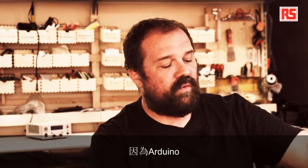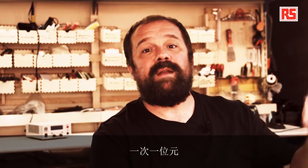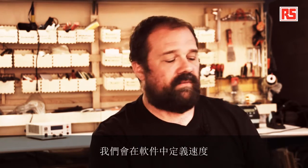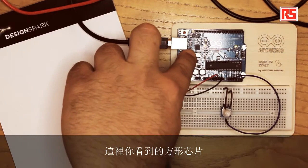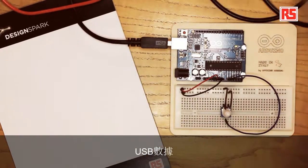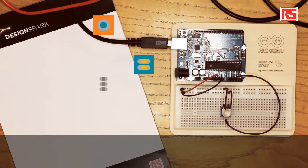So we're going to be using for this project something that's called serial communication, because the Arduino will send data over to the computer one bit at a time at a certain speed that we will define in software, and then the square chip that you see here will convert that into USB data that travels over to the computer.